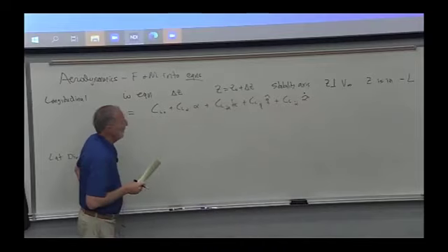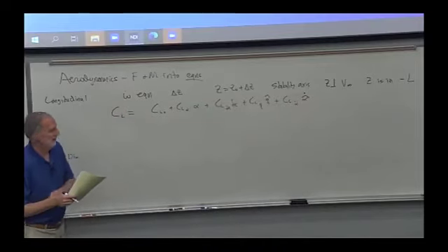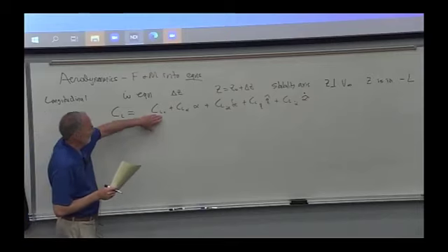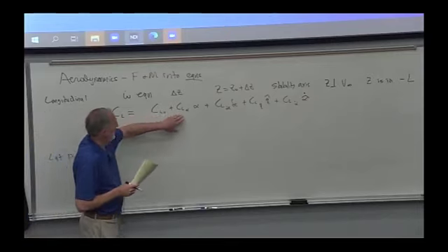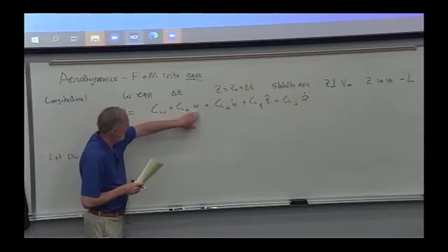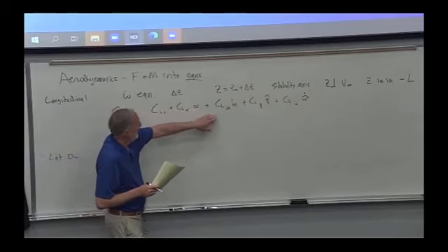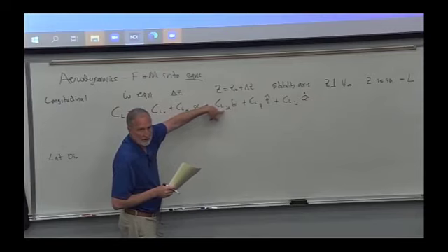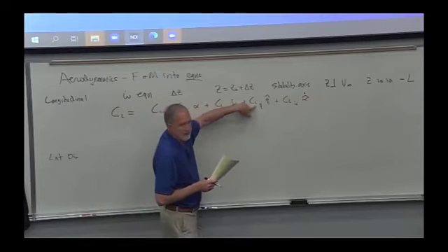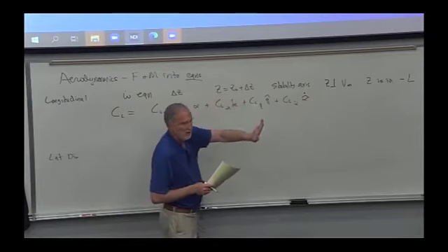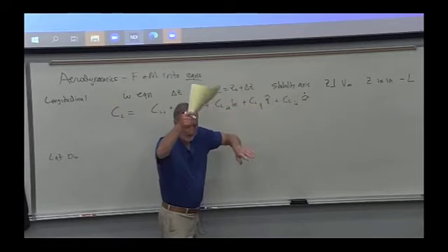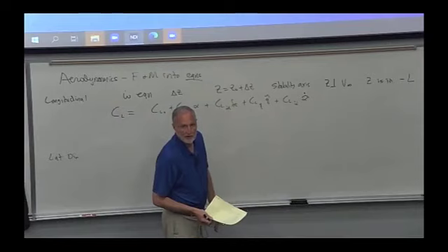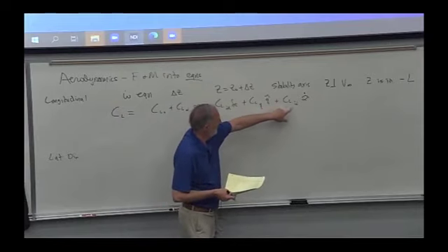And so those are the variables that we say the lift depends on. And they're the normal ones, right? We have some zero lift, or we have some lift at 0 alpha. And then this is our lift curve slope times alpha. This is for the whole airplane. And then the elevator changes the lift, right? And then when we talked about a pull-up, the airplane's pitching. And so we have to get some lift due to the pitch rate because the tail is sweeping down. And we added that in the pull-up, but this is new.